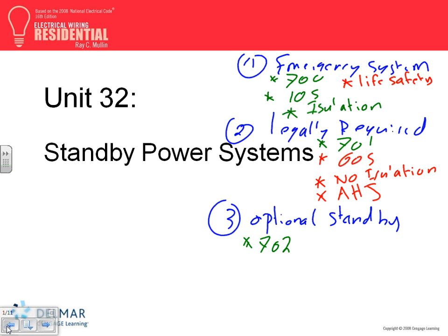The authority having jurisdiction, a government agency in the area, decided that in case of a fire or an emergency, all the receptacles in a 911 calling system are to be energized. These are not people's lives. We can argue that in the building, people's lives are not dependent on them, but they're required to be hot within 60 seconds.